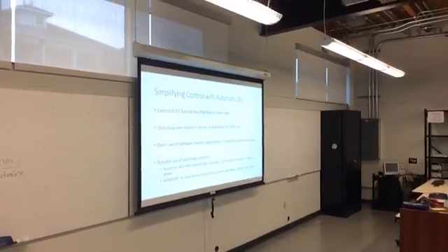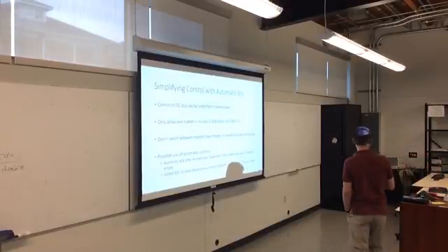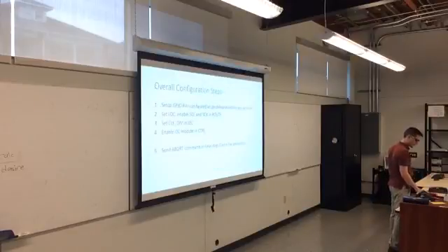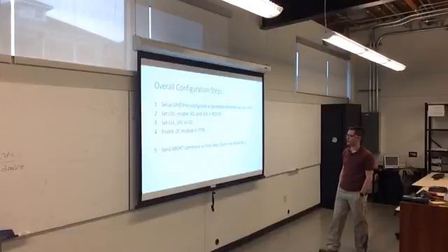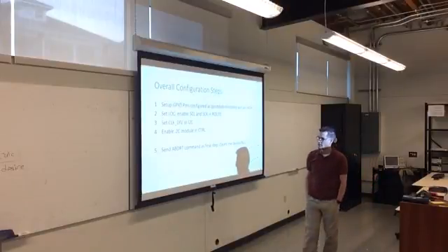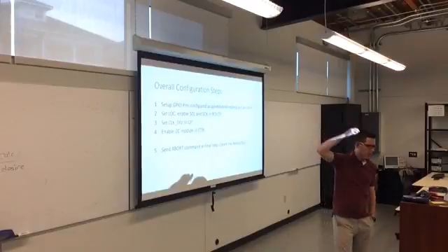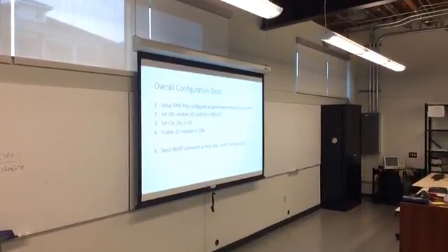Here's the overall configuration that you need to do to get this up and running. The configuration is a lot easier. When you pick your pins, you have to put them in a mode called GPIO wired-AND, and you have to set output high, which means they're going to naturally float high, and then they can be pulled down low.